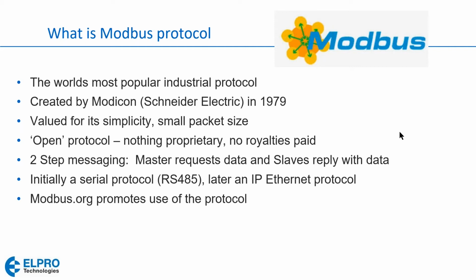And Modbus is valued for its simplicity. It really is absolutely a dead simple protocol, especially when compared to all of the other protocols that are out there on the market, like 802.11. Even Allen Bradley's Ethernet IP is substantially more complicated. And as well, Modbus is an open protocol, so there's nothing proprietary about it. You don't have to pay any royalties to Schneider Electric or anything to be able to use it, to have it designed or built into your product.